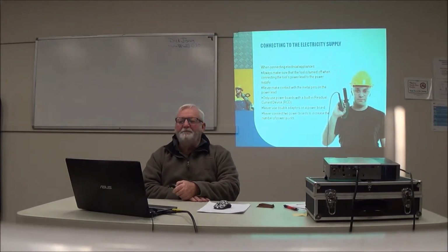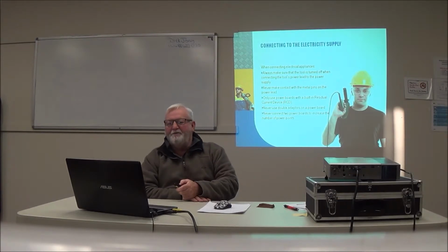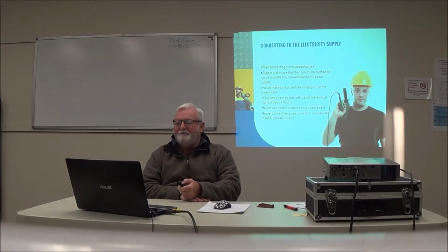When connecting electrical appliances, always make sure that the tool is turned off when connecting the tool's power lead to the power supply. Never make contact with the metal pins on the power lead. Only use power boards with built-in RCDs, which are called residual current devices. Never use double adapters on a power board. Never connect two power boards to increase the number of power points.